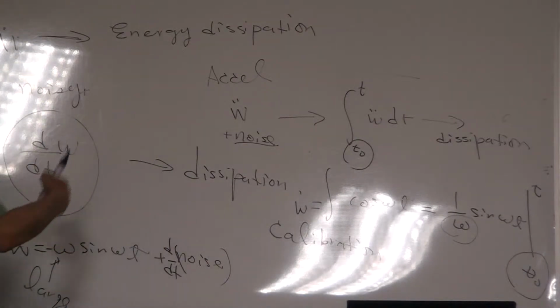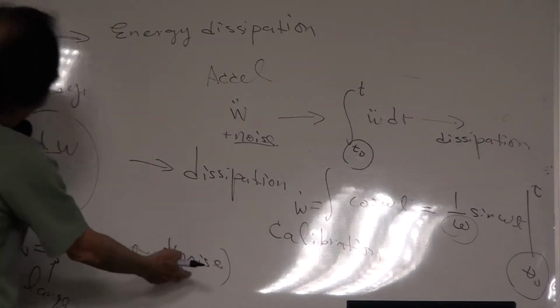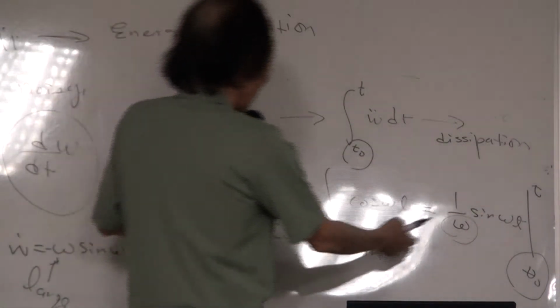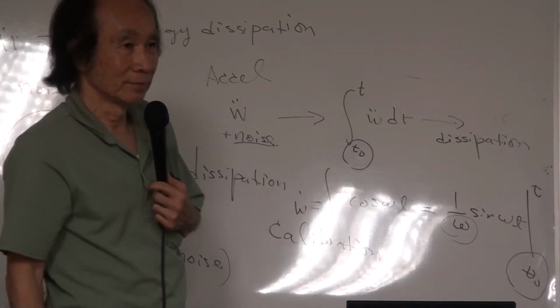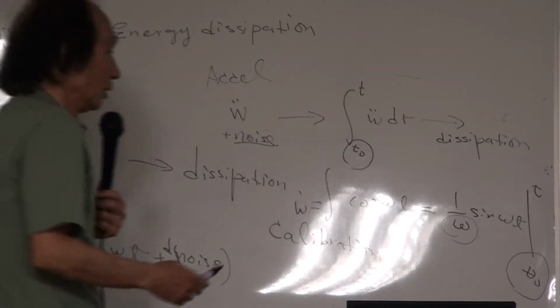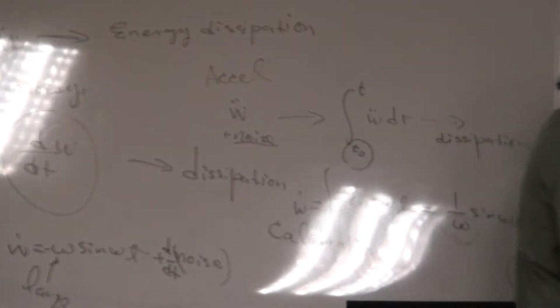You can differentiate the signal and you got a velocity. Yes, that's true. You gotta worry about the noise because you amplify noise when you differentiate the signal. You reduce noise when you integrate the signal. That's true too, right? So that's what happens for these different sensors.